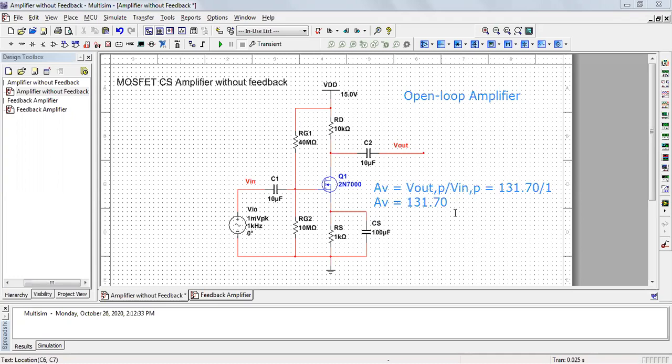Okay. So what is the solution then? We have to reduce the gain of the amplifier to our desired, required value. We should have control over the gain of the amplifier. And that gain value we can control by providing feedback, but not positive feedback, a negative feedback. Because we want to reduce the gain. We don't want to increase the gain. Clear?